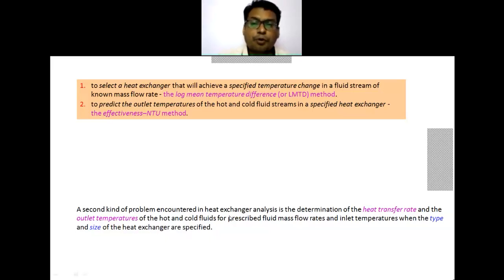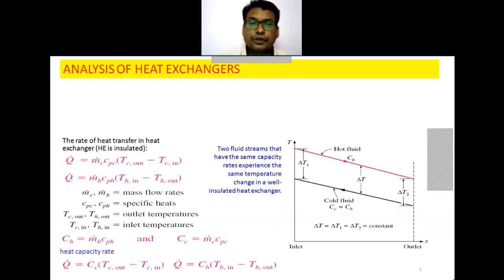So the kind of problem encountered in heat exchanger analysis is the determination of the heat transfer rate and the outlet temperatures. Not only the outlet temperatures, we are also determining the heat transfer rate for the specified fluid flow rates and inlet temperatures. Now, in the analysis of the heat exchanger, we have the co-current as well as the counter current flow.